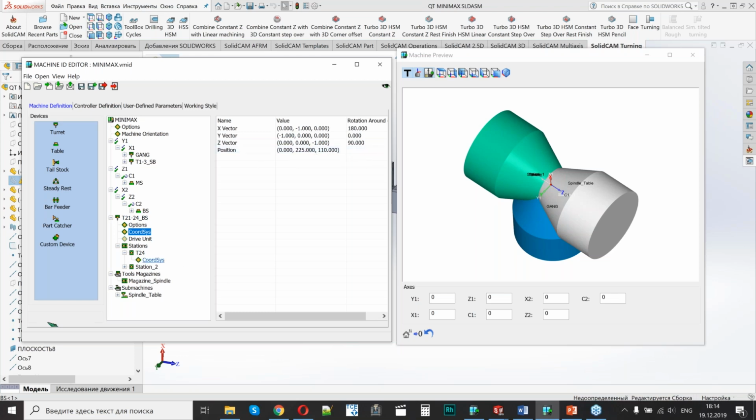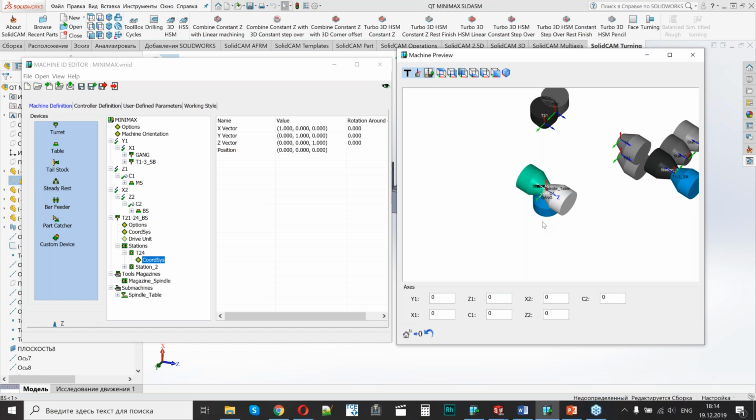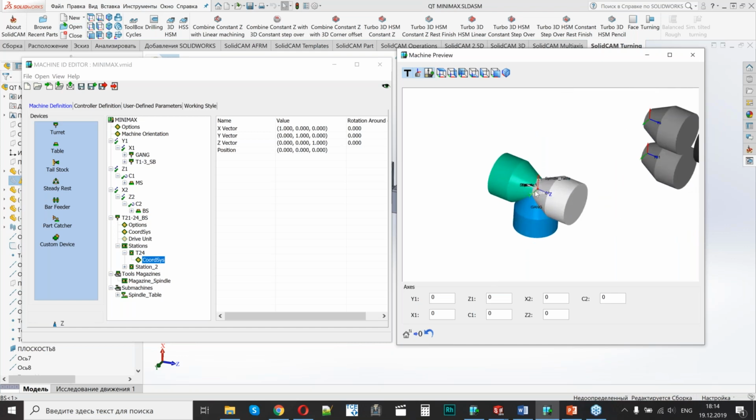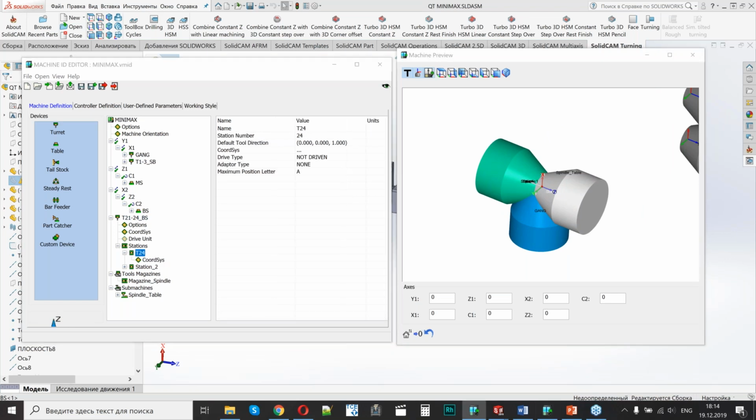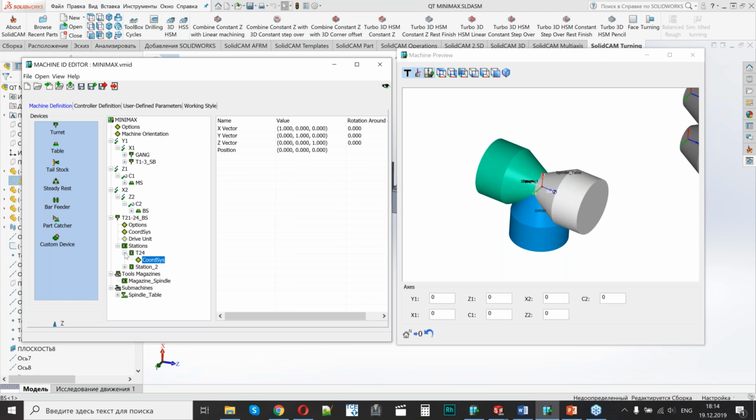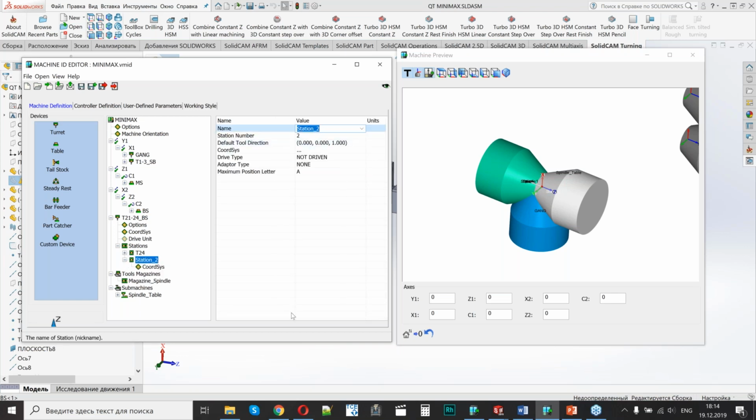It is already shifted. We have related coordinates here. They are not absolute. And I will take care of the position of the coordinate system. Here I have my z direction, the right direction, and my default tool direction will be the same. It should be like 1 according to the z position. So it can be checked very easily on the machine during the tool mounting operations.